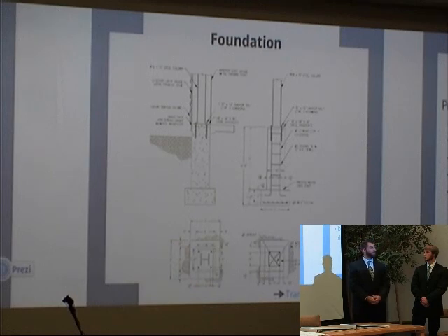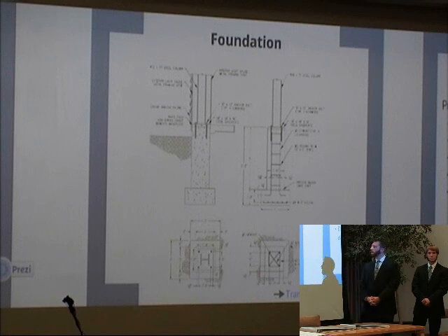And what this did was, over a 3-foot square area, it came out to about 60 psi on the ground surface, so really relatively low. Most of your running larger trucks put out about 100 to 120 psi on your ground surfaces. Some performance tires on a light car put out 65, so the actual bearing on the soil is quite light.